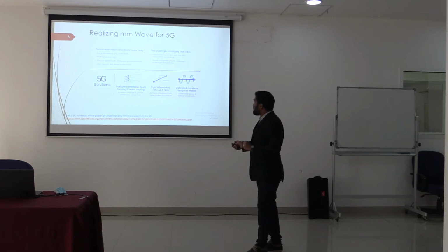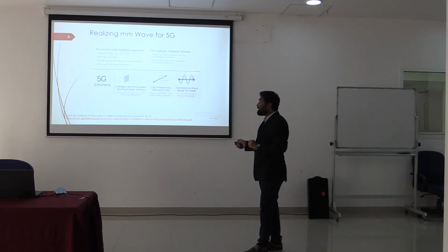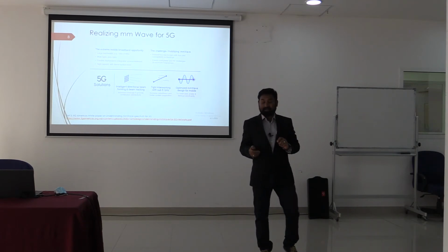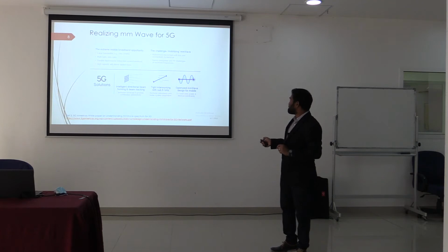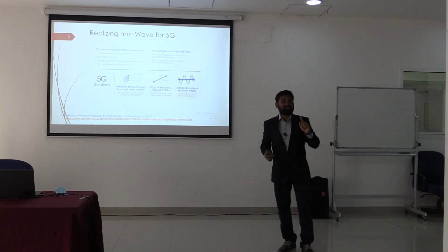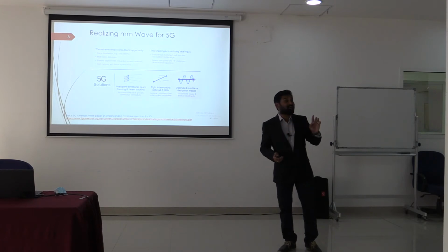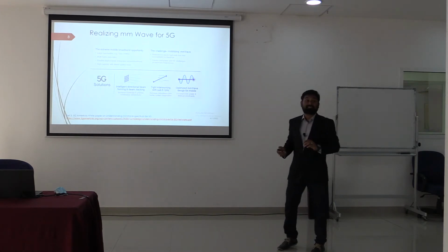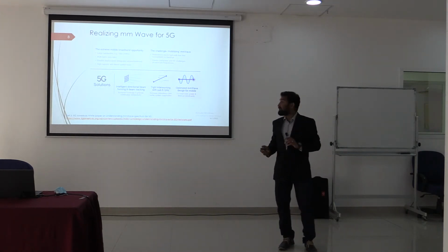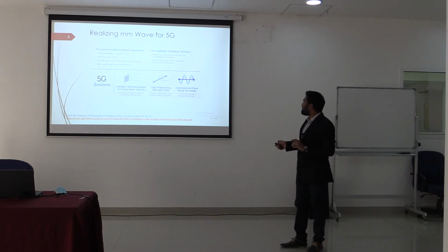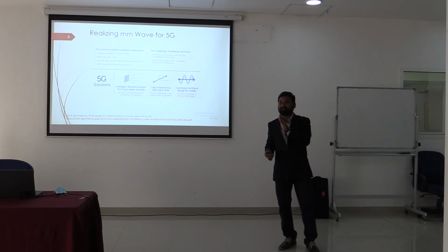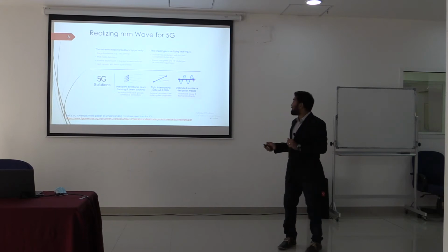And it has high capacity with dense spatial reuse. This is the concept. The spatial reuse concept is not a new technology, but still that particular technology helps this 5G to be implemented in a better way. What are the challenges? As we already mentioned, these millimeter wave frequencies cannot travel a long distance. We know that. So the susceptibility to blockage will result in high blockage. The second one, as I already mentioned, is the RF power amplifier challenge with the 1 dB compression point. I told you, linear region to non-linear region operation. So that is the second challenge.